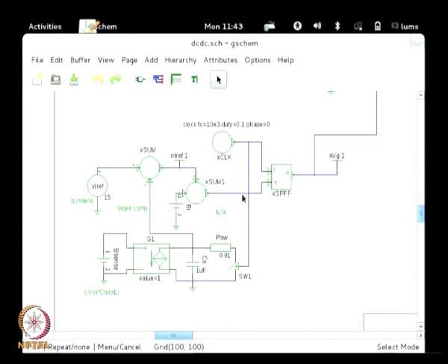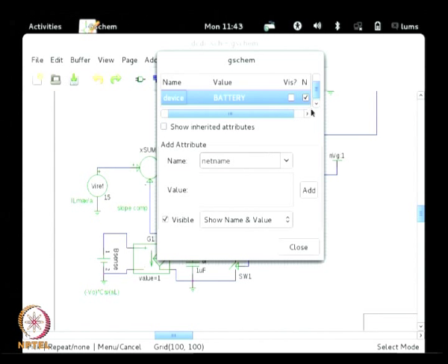Now, to the reset pin is connected the comparator output from these 2 points. This is basically the measurement of the current which is fed back from the inductor. This is actually a B source, wherein you can put in an equation.